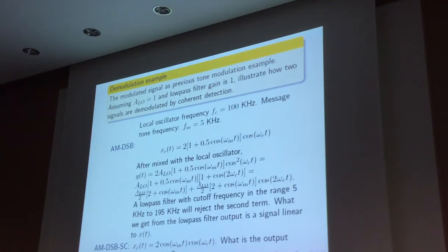Alright? Then we can find out, once we determine the order n, so how to determine order n? We need to solve an inequality, define the minimum integer number n, satisfying the inequality. Because we know that in a rolling off region, a low pass prototype rolls off at 20 times n dB per decade. To solve this inequality, we can find out the order of the filter, right? Then once we solve the n, we can determine parameters from G1 all the way to Gn. Depending on the configuration you're going to use, you can interpret it into the value for capacitor or the value for inductor.